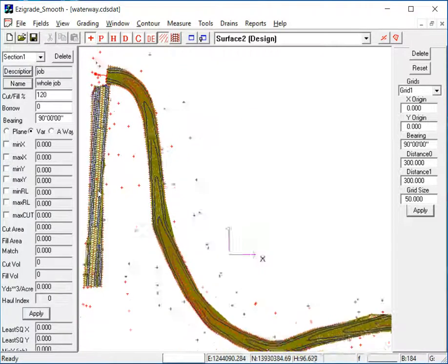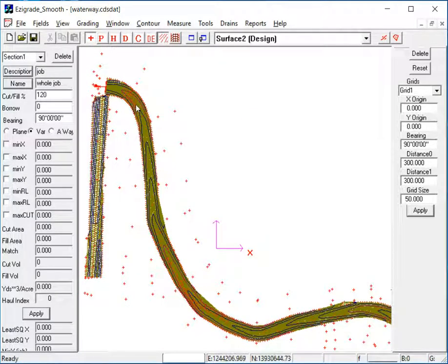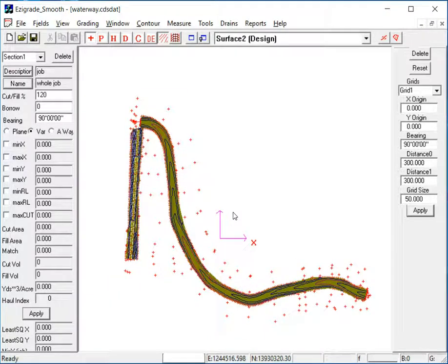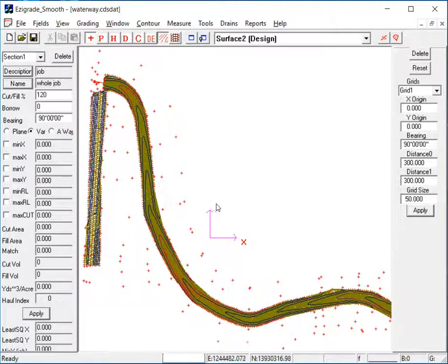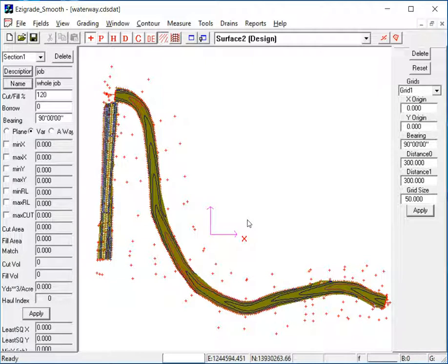The surface out is only as good as the contours here. Now they look alright. Just be aware, the contours that we imported came from a different package, maybe Civil 3D or similar, and we've reformed the triangles, so they could slightly change. So just check the contours. If they do change, you can go back and do the surfaces independently and use the triangles as they were imported.